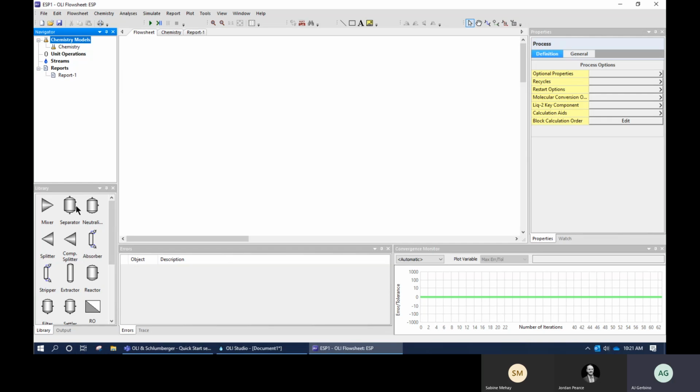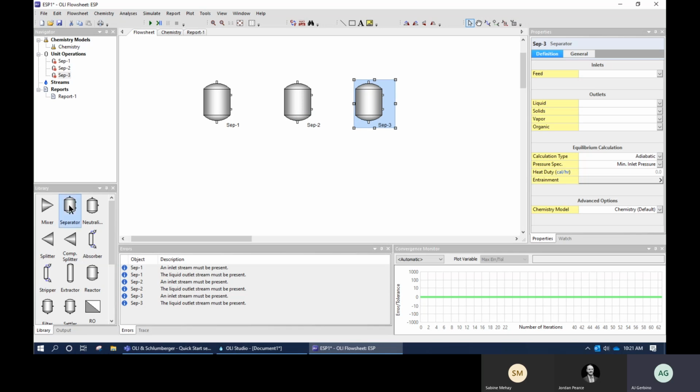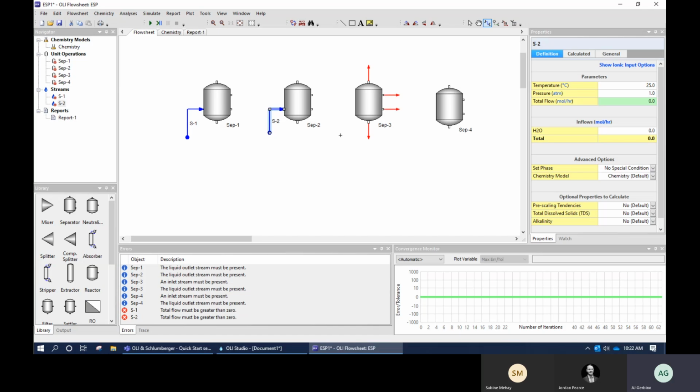What I'm going to do is create a series of what we call separators. Each one essentially is going to represent a different section of the reservoir. And I'm going to add fresh mineral to each step. Essentially, we're going to flow the acid in this direction, and it's going to react with that part of the rock. I'm going to let the mineral stay present there.